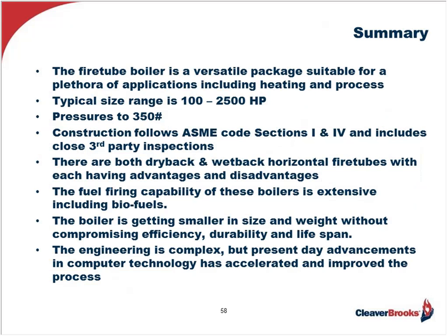The fire tube boiler is a versatile package suitable for a plethora of applications. I've only cited a few in this PowerPoint presentation this afternoon. Typical size ranges between 100 horsepower up to 2,500 horsepower as packages. Pressures up to 350 pounds. Construction, we follow the ASME code, all of us, very, very closely. Sections 1 and 4, 1 being high pressure, 4 being low pressure.